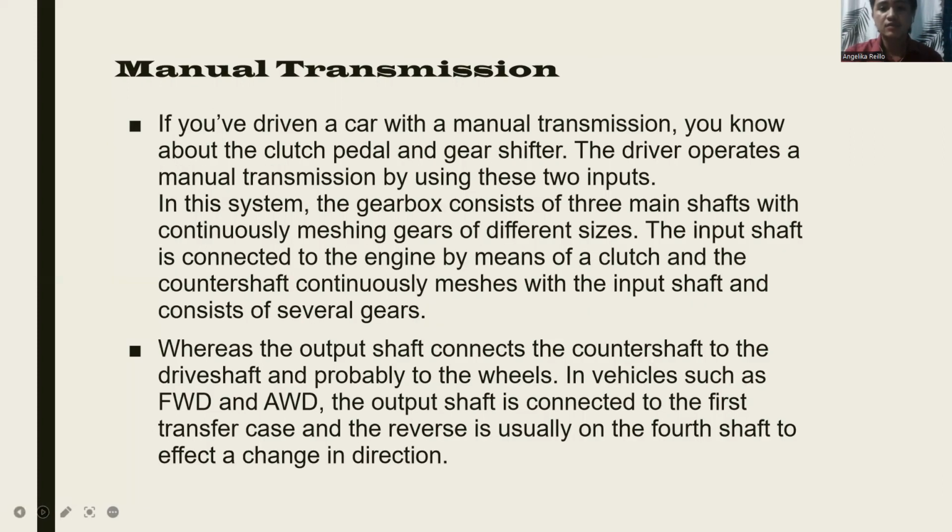whereas the output shaft connects the counter shaft to the drive shaft and probably to the wheels. In vehicles such as FWD and AWD, the output shaft is connected to the transfer case, and the reverse is usually on the fourth shaft to effect a change in direction.